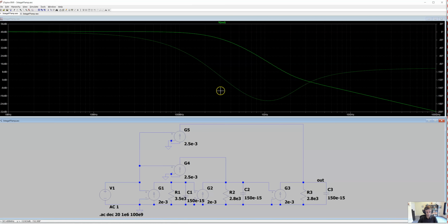Now, if we look at the magnitude response at 500 megahertz, that's around here, you'll notice that we've still got a magnitude response of about 34 dB. So it's the same. It's about 50 volts per volt at 500 megahertz. However, the DC gain is a little lower, but that's okay. It's still meeting our spec requirement in band. And let's check our phase margin here at the 0 dB crossover, the unity gain crossover frequency. It's now lower than before, again because of the steeper roll-off, but we've still got a phase shift of about minus 135, so about 45 degrees phase margin.